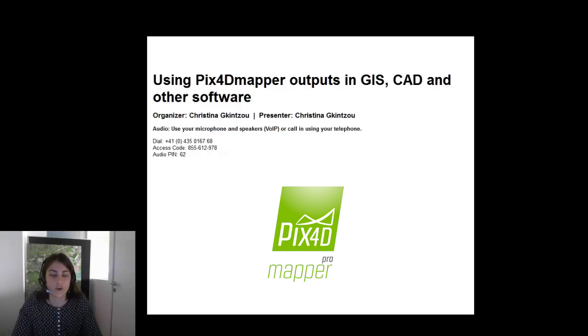It has also color information. Practically, it is a 2D reprojection of your area. As a 2D projection of your area, it doesn't have altitudes. So if you are interested also in altitude information, then you should work with the DSM. The DSM does not have color. It has altitude for each pixel of the orthomosaic.